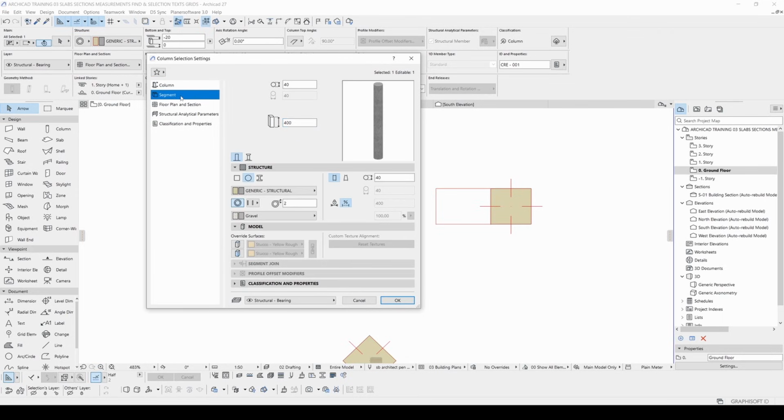If you go to segment, you can add more segments for your column. To do it, we will just click this multi-segmented, and we will add a couple of segments, and you can click each segment and change its size. Now it works with percent, 25%, or you can input a fixed height. For instance, I want this to be 1 meter. I want this to be 1 meter. And this is going to be 2 meters, so in total 2, 1, 1 is equal to 4 meters.